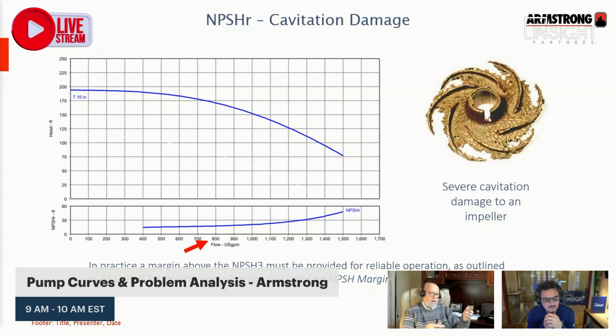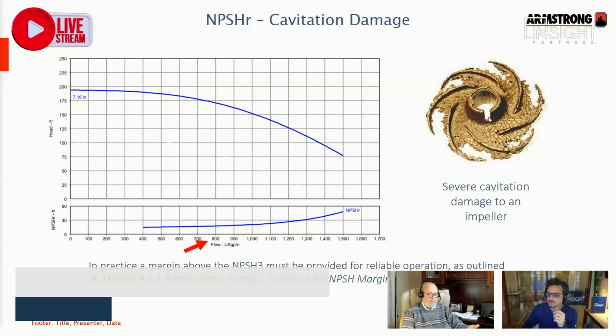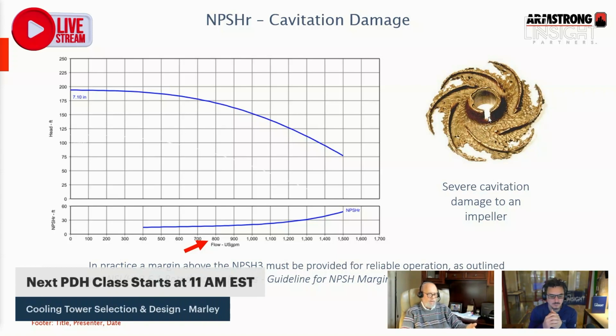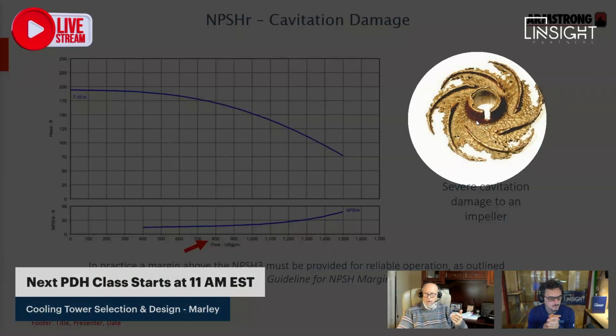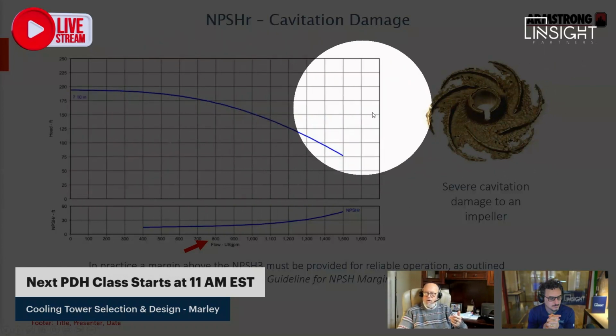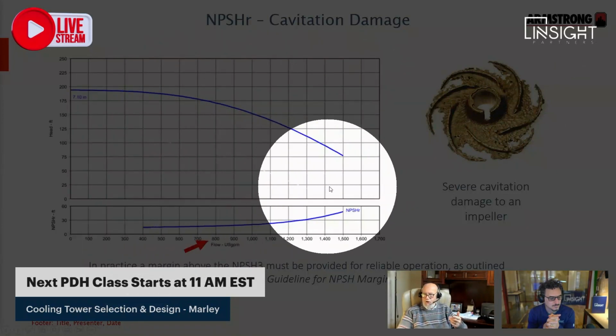And if I look at it and I understand that, I can take that into consideration when I'm calculating the capacity across the pump and where that pump is actually running on its curve. And so just so everybody understands, when I look at a pump curve, okay, so here's my pump curve. This is showing the NPSHR curve.